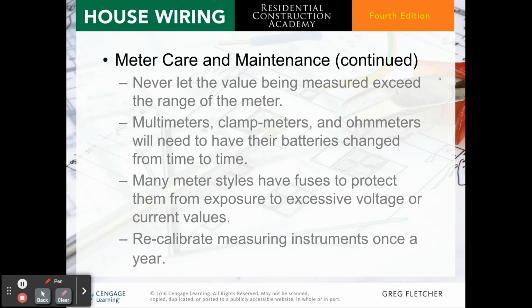Multimeters, clamp meters, and ohmmeters need to have their batteries changed from time to time. Many meter styles have fuses to protect them from exposure to excessive voltage or current values. Be sure to recalibrate measuring instruments at least once a year.